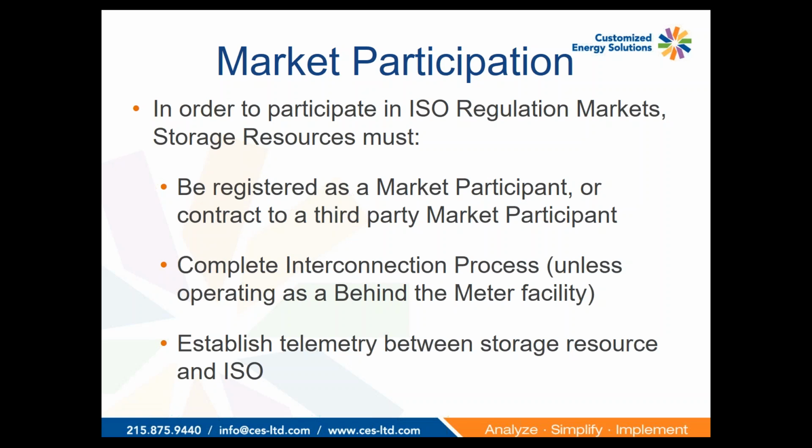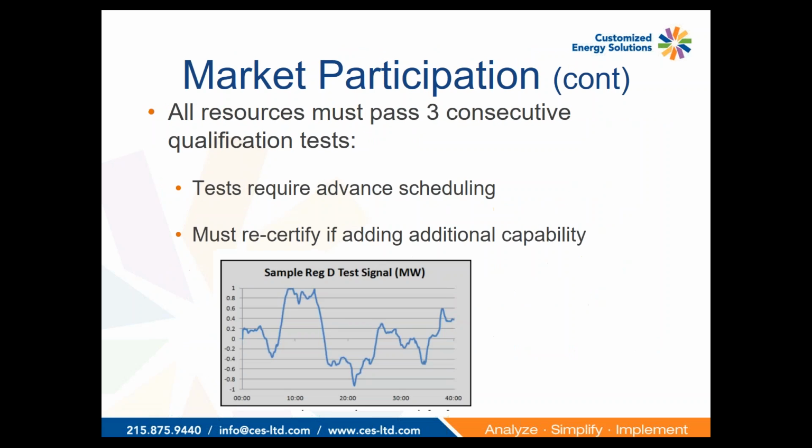And then lastly, telemetry requirements. The ISOs all want to see what the storage facility is producing at every instant in time. They need to have very near real-time information to be able to calculate their performance scores, and typically they need to establish private network connections or some sort of virtual connection to the facilities, and again, that can take some lead time. We've seen several instances where storage developers have not realized that, waited till the last minute, and are basically ready to come online, but then have to wait several weeks in order to get that telemetry in place.